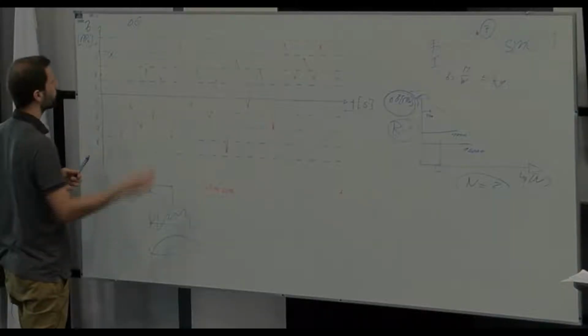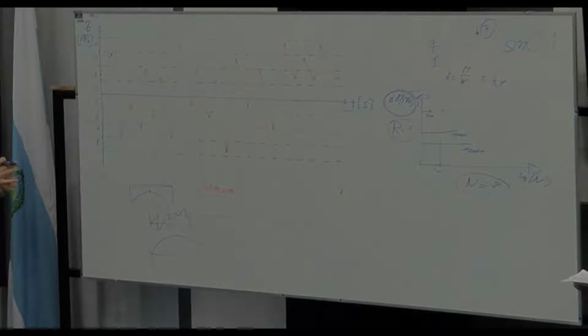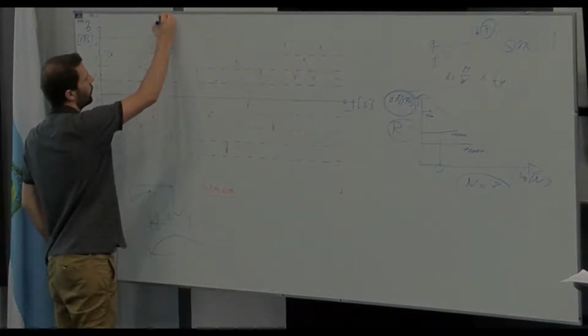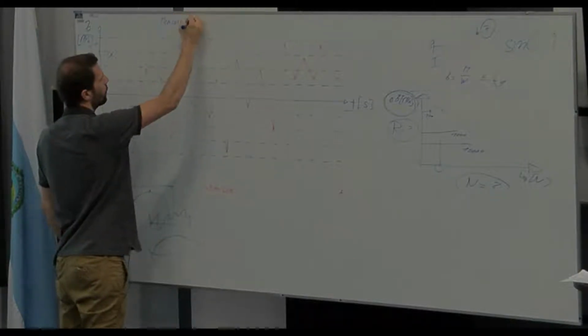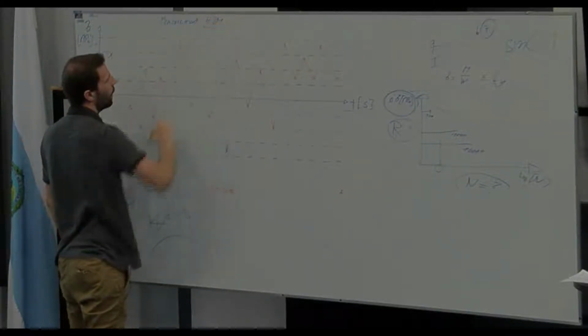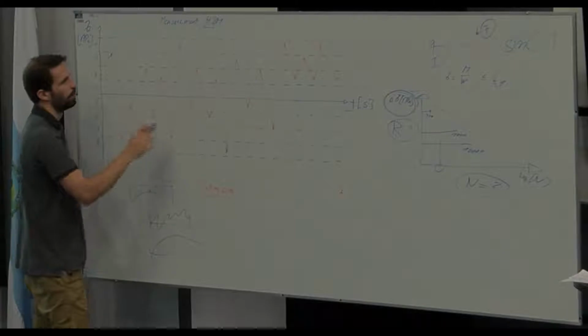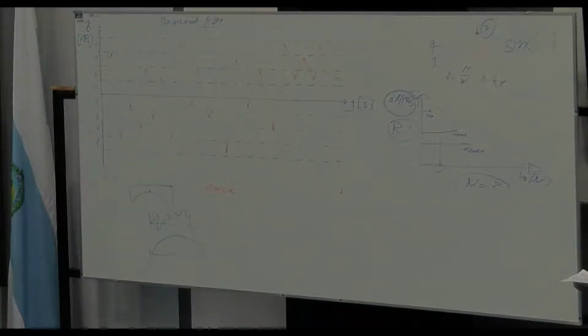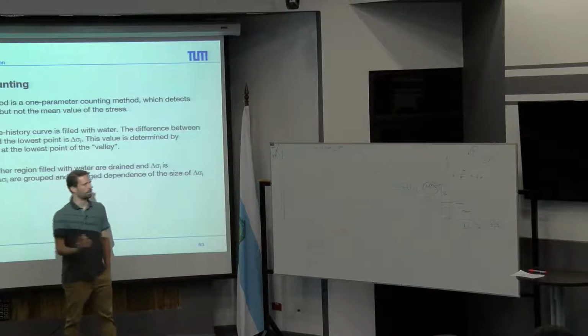So, what are we doing? For example, if you go for a time signal like this, you can find, for example, I saw in your laboratory you had some measurement tools from HBM, and in these tools there are already some cycle counting methods included. So if you apply a strain gauge on a system, you can already say, okay, please use the information from the strain gauge for a counting method, and you get back the information.